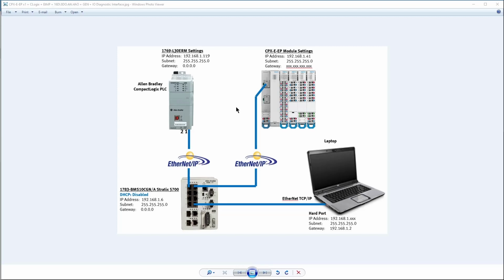The reasoning behind showing this in the first place is that Rockwell PLCs, whenever you buy them, typically have a limitation on the amount of Ethernet IP connections that they can have. Establishing one connection to this module to get process data is one connection. If you want to get additional, very detailed information, as in my last video, you use explicit messages, and in that case you create another connection. So one module here would have two connections,